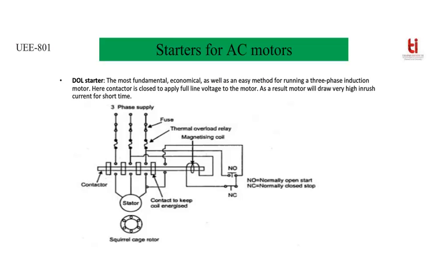You can see the rightmost contactor will give a path to the magnetizing coil through the stator. The main disadvantage of this method is that initially it will draw a larger amount of current. So this method is not preferred for high power rating induction motors.